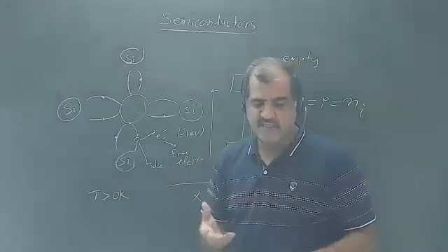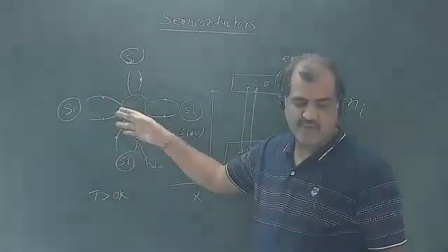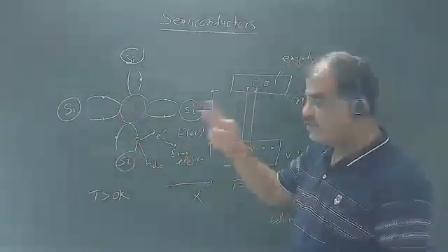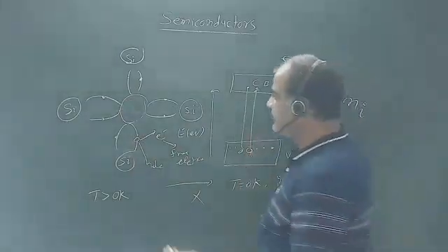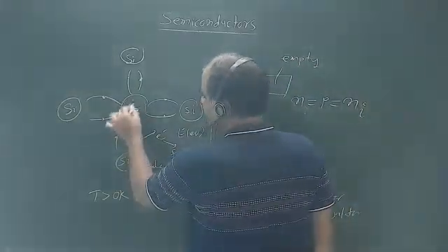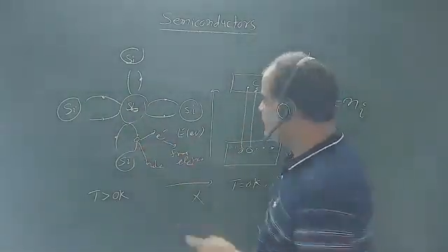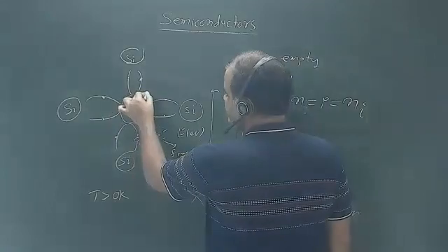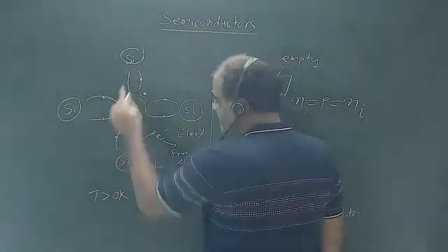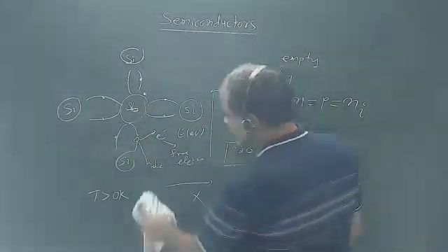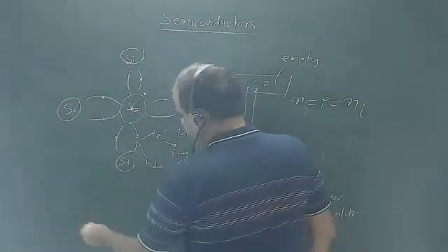I want to replace silicon. Out of 100, I replaced 1. Out of 100, I replaced 2, with some 5th group element like antimony or arsenic, which is a 5th group element. So this 5th group element will have 1 extra electron, which will be very loosely bound. So these are examples of n-type material,